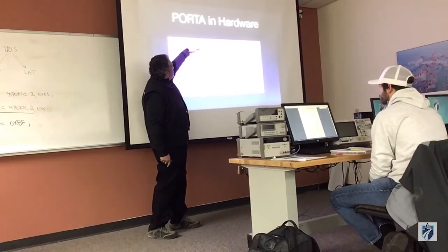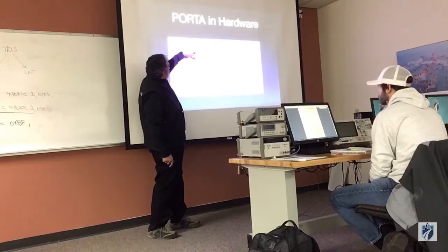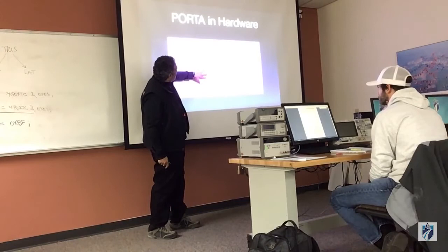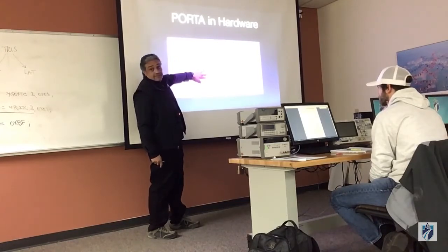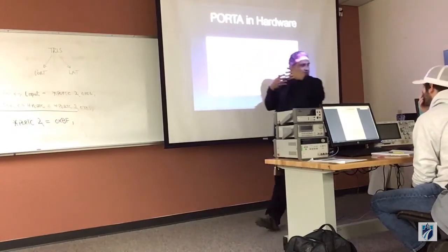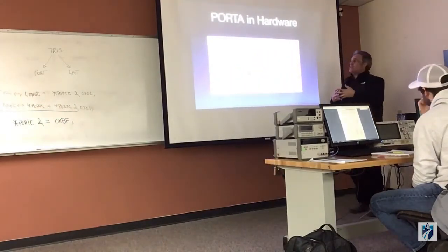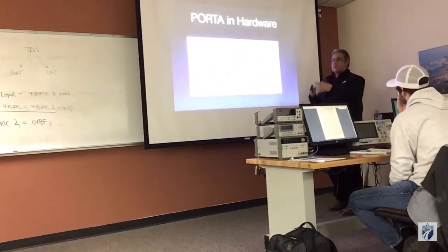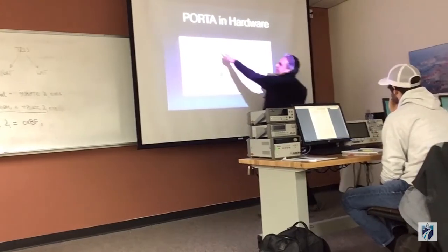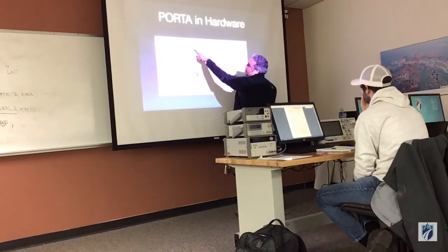You're going to have A0, A1, A2, 3, 4, 5, and there is 6 and 7 actually split on pins 13 and 14. See that? But I want you to notice that multiplexed in the same physical pin, there are more hidden behaviors. And every behavior is a circuit, by the way. So you have a digital circuit and an analog circuit in the same pin.